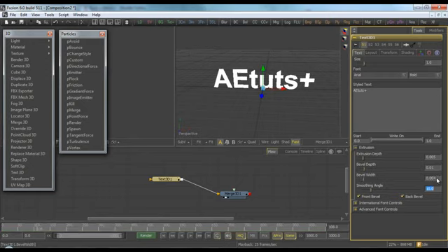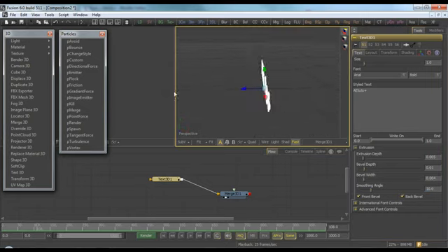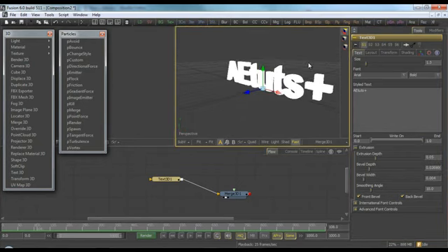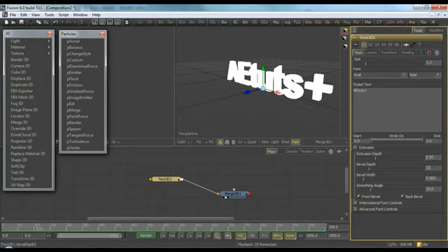0.04. That's right. As you can see, we have some extrusion. Oh, I messed it up. Extrusion depth will go to 0.05. Yeah, that's much better. And bevel will stay the same, 0.01 or 2. Okay, I'm fine with that. And bevel width 0.004. Yeah, that's right. And we're gonna smooth it quite a lot, and we'll increase it to about 50.